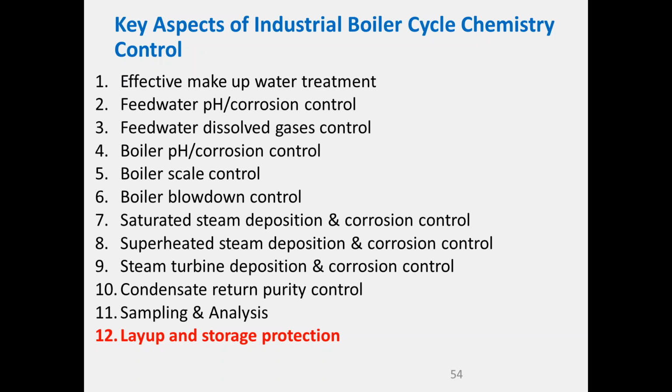And if you've got a heat exchanger where the steam or the condensate is at a lower pressure than the process, so it could leak back, and that's milk or hydrocarbon or seawater or something like that, then you need some kind of condensate return contamination detection, and a conductivity meter would probably be the simplest and most basic one there. If you have a superheater on your plant, at a bare minimum, you need a sample point which